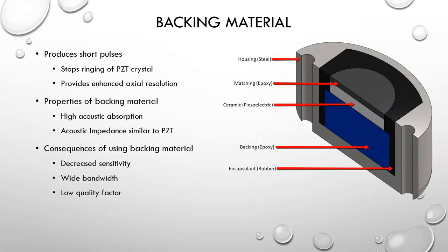Some of the properties that backing material will have are high acoustic absorption, so they absorb a lot of the sound that's created by the crystal. And you want to have a backing layer with a very similar impedance to the PZT crystal. Again, that allows the sound to go into the backing layer and not to remain in the crystal.